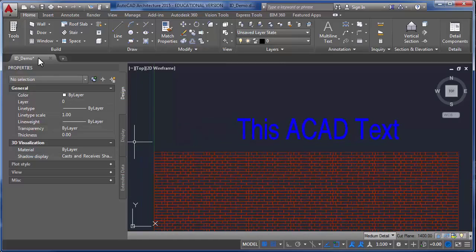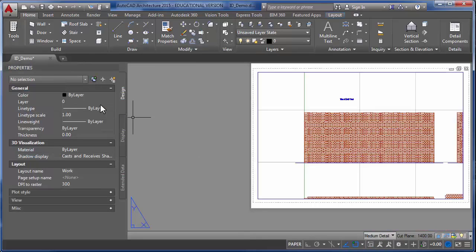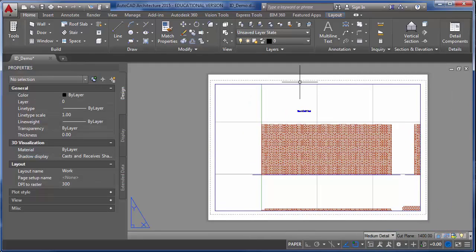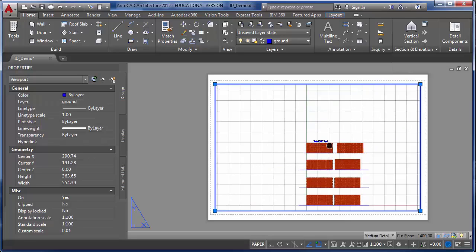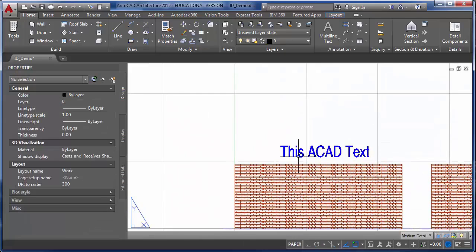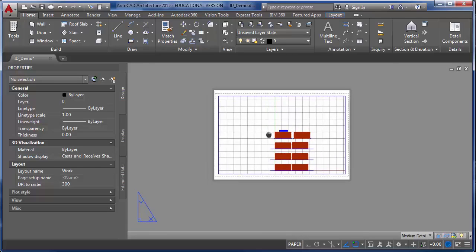And when I go back to my paper, I would need to adjust the scale here. Here it's the original one. One way I've taught you before is to select the frame and change it in the properties. I've also found out when you select the frame, there's a dialog that pops up here, so I can change this to 1 to 100, and you see the text did update. So let me come back out. This is at 1 to 100. Do a distance: 5 millimeters, right? So it is automatically adjusting the text.